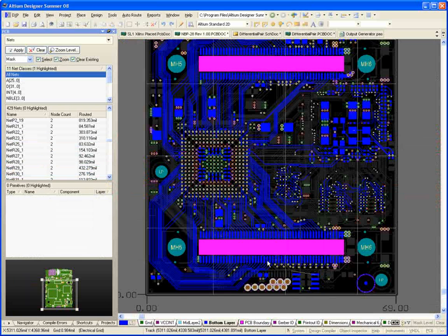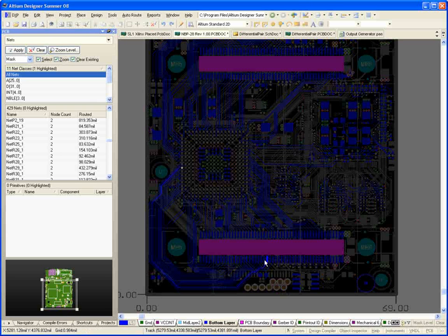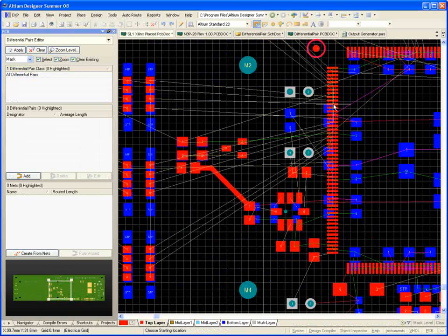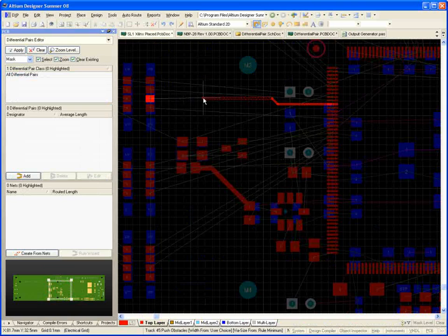And using Altium Designer's combined features of interactive highlighting, layer sets, and single layer mode, the challenges of routing even a complex board become so much more than just manageable. I can highlight whole nets by simply holding Control and clicking on any net object. Nets also become highlighted on the fly during routing.